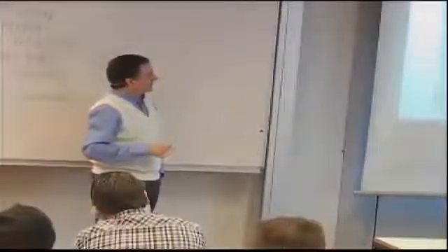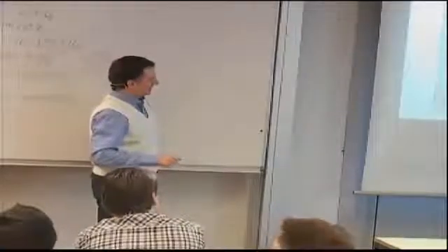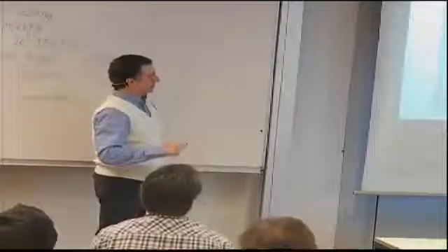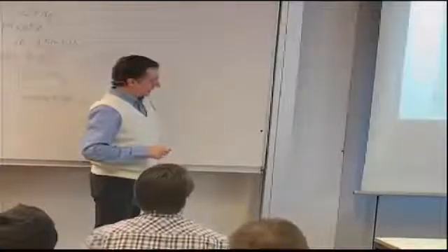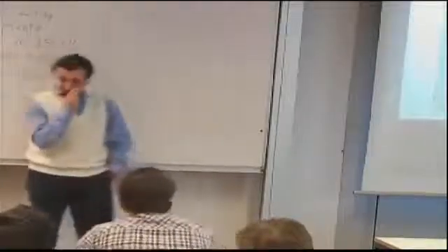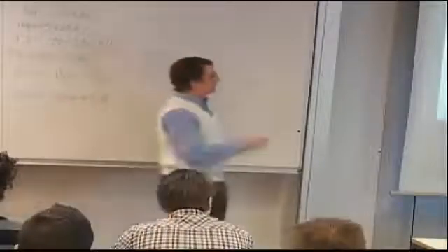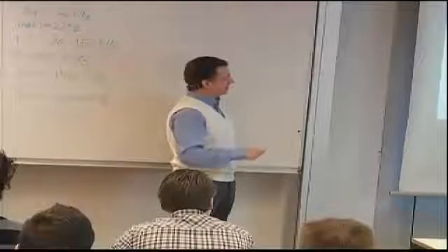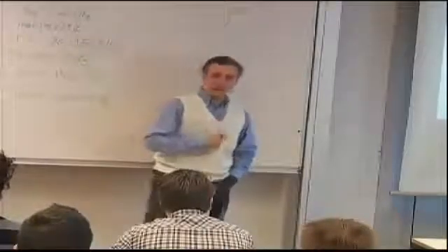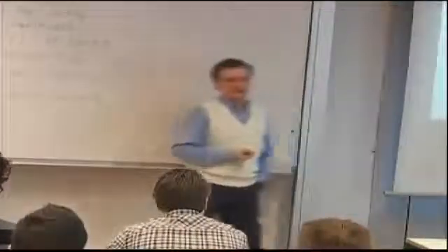So if you take all these, if you take material scatter alone first, then, for example, this is typical tension strength data, and this is the strength in megapascal shown on the x-axis. Then the distribution of the tension strength is here. And for the exact same material, the distribution of the compression strength is here. Typically, compression is slightly less or significantly less than the tension. Obviously, you cannot take the average value, because if you take the average value, then there's a whole bunch of material that would be coming in with strength lower than the average that you could be using, and you had assumed the average value, and obviously you're being unconservative.